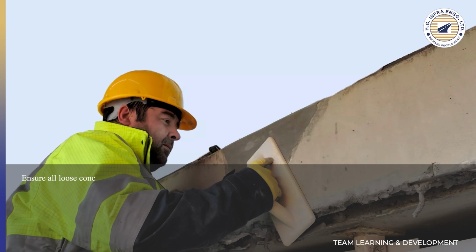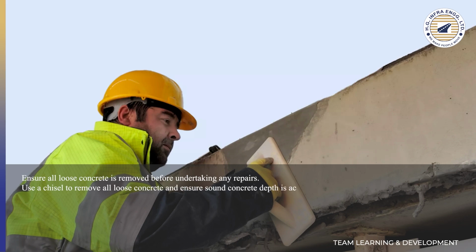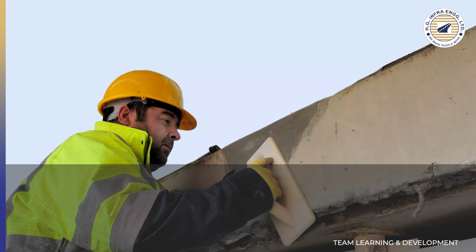Ensure all loose concrete is removed before undertaking any repairs. Use a chisel to remove all loose concrete and ensure sound concrete depth is achieved. We will now discuss the minor repairs, that is cosmetic repair.